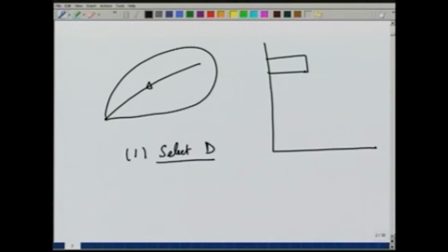If we have a rainfall of shorter duration, the intensity would be higher, in such a way that I1 d1 should be equal to 1 and I2 d2 should also be equal to 1. And naturally, these two different rainfalls will give us different hydrographs.